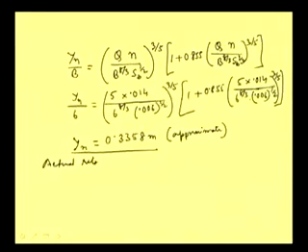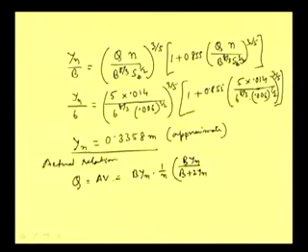then we will have to write our original equation, that is Q is equal to area into velocity. So for rectangular channel we know that area is equal to B yn and velocity is equal to 1 by n, writing Manning's equation, area and then perimeter B plus twice yn to the power 2 by 3, then bed slope to the power half. Now here we know the Q, but we cannot solve for this yn directly.